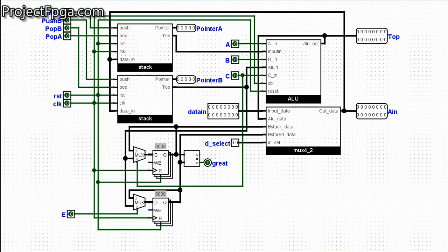So this is basically how this area is used, and all these A, B, and C signals that are used to open all those multiplexers are coming from the control signal. When we talk about the control signal, I'll show you how the A, B, and C signals are generated. Now let's talk about this multiplexer again. Before that, you also see that the inputs going to registers A and B are coming from the first stack, because that is where the figures are stored. Whereas the LU in is coming from the second stack, which stores the operators. The arithmetic operators come from stack 2. So that is how the numbers go to one stack and the operators go to the other.